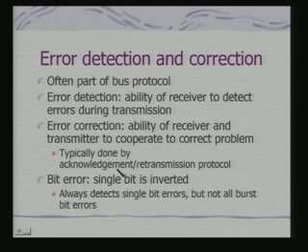But when you are doing an isochronous transfer, you really do not have a provision for retransmission. So, there has to be some kind of post processing to take care of those errors. What kind of errors can occur? The simplest error is bit errors. Okay. So, here a single bit is effectively inverted. So, when we try to detect a single bit error, we can detect single bit errors, but not all burst bit errors can always be detected.